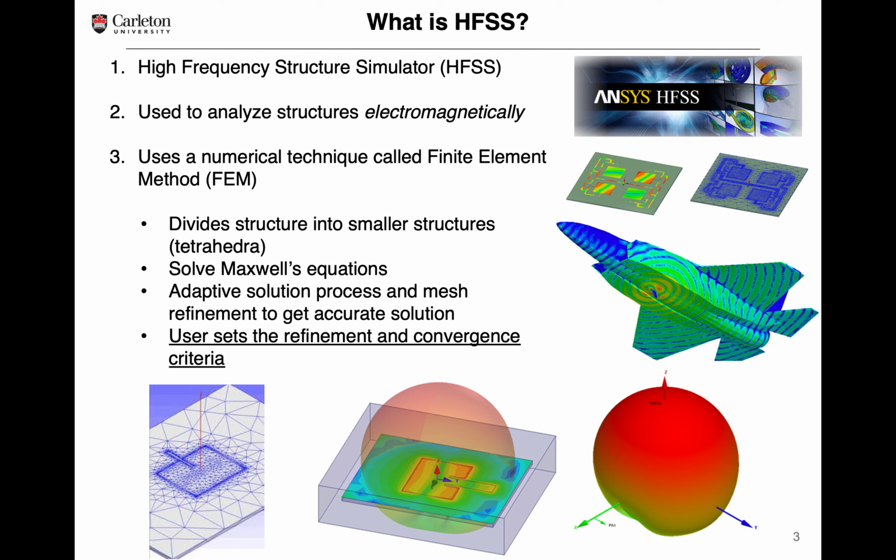And the accuracy of the solution depends on the convergence criteria that the user sets. So when you run the simulation, you would tell HFSS what you consider as an acceptable margin of error, and we'll discuss that today when we run the simulations.